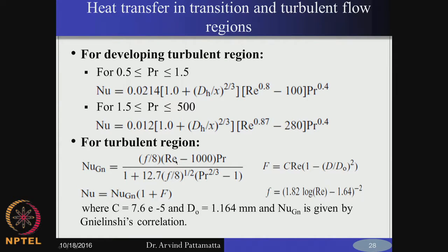Okay, is that clear? In the case of Nusselt number, we have not developed anything specifically for microchannels. All of these correlations are already there for the macro channel case that we have directly taken. You only have to be aware that, if you are dealing with roughness, you use the same concept of constricted flow Reynolds number in this correlation.